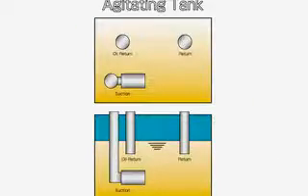This is an ordinary tank. In the tank, the oil return and suction portions are in close proximity, so the oil is stirred, which disperses and propagates the amount of sludge. This causes oil contamination to progress. Let's modify this tank and transform it into a cleaning tank system.